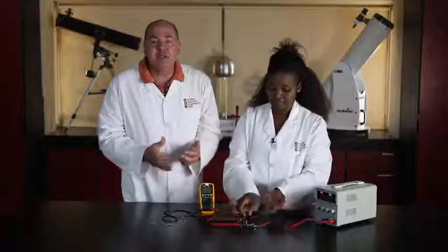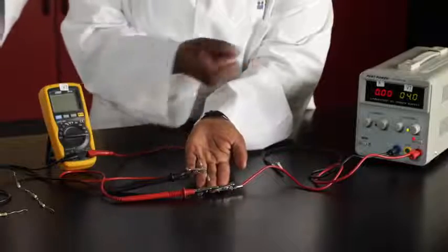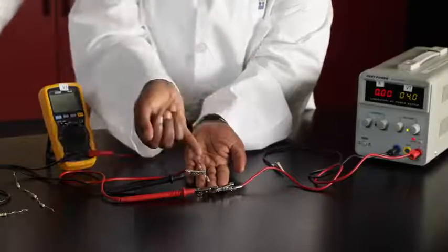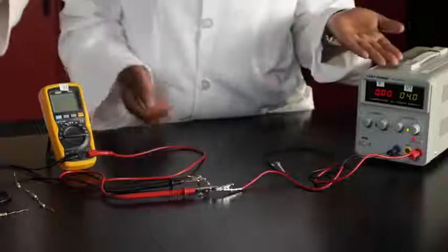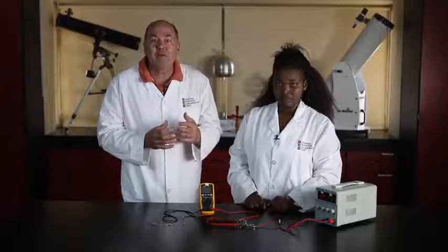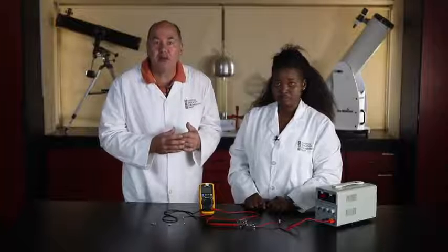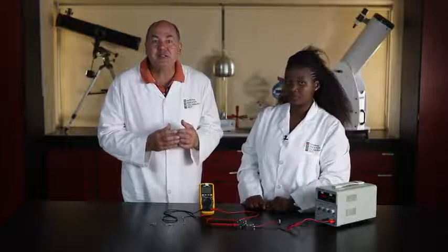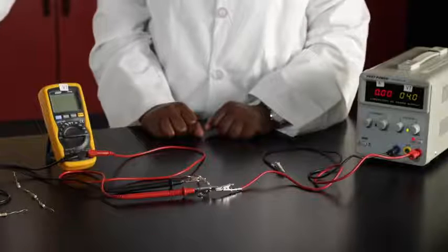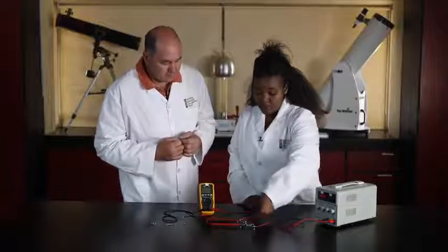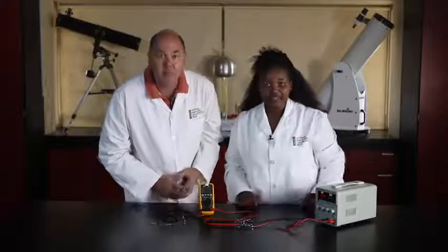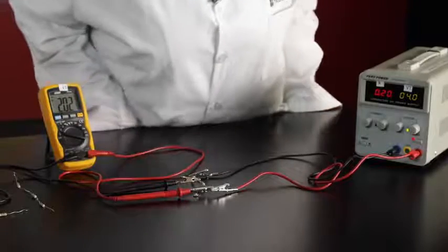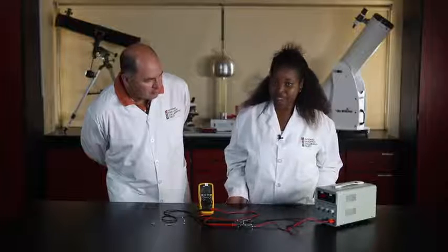Now we add another resistor R2, and we do this by putting it into series with resistor 1. All the ammeter and voltmeter connections remain the same. The switch connects the second resistor to the power pack, so we are ready to take the second set of readings. Yes, I am closing the switch. And we have current passing through the circuit. The current is 0.2 amps. It's half the value that it was with one resistor.